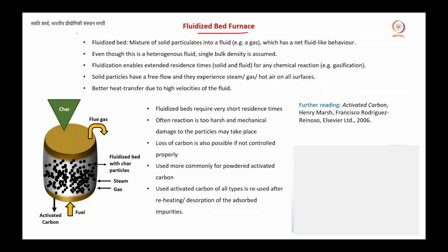In a fluidized bed furnace, you have a mixture of solid particles and fluid which has a net fluid-like behavior. Even though this is a heterogeneous fluid, a single bulk density is assumed. Fluidization enables extended residence time for any chemical reaction or gasification. Solid particles have a free flow. They experience steam and hot gases on all surfaces. Better heat transfer is achieved due to the high velocity of the fluid.